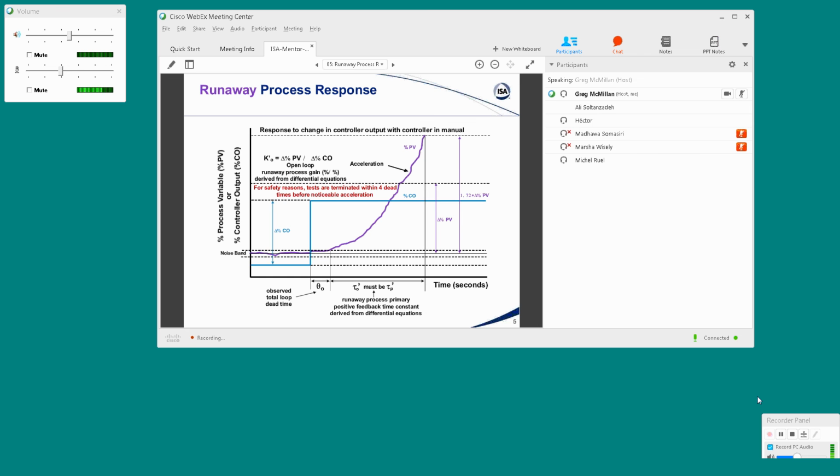Very good question, because I've seen those cases presented, and honestly, I didn't take the time to argue about it, but I thought through them and realized you could present a case where the dead time was large and the secondary time constant was not, and then the conclusions were the opposite, as well as the value of lambda tuning versus conventional tuning rules that don't set the derivative action based on secondary time constant. It requires greater sophistication to identify the secondary time constant.